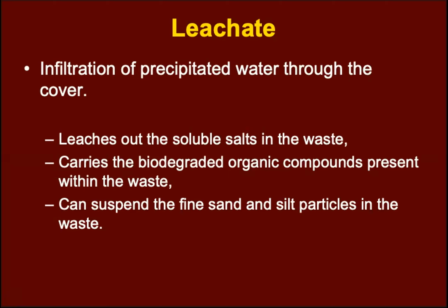This liquid will dissolve the different contaminants present in the waste, leaching out the soluble salts, carrying the biodegraded organic compounds, and suspending the fine particles in the waste, forming a liquid leachate that accumulates on the base of the landfill, where there typically exists a leachate collection system that would take this contaminated water and transport it to be treated.